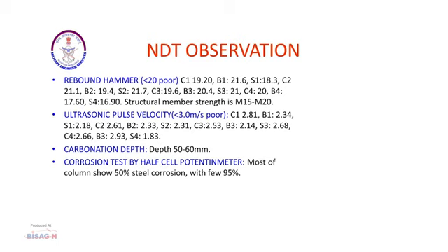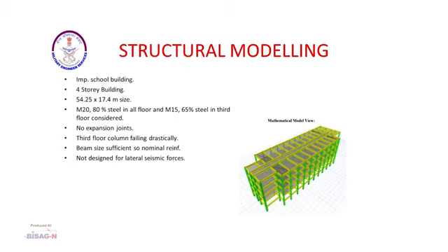That started with NDT testing. We did rebound hammer, ultrasonic pulse velocity, carbonation depth and corrosion test by half cell potential meter. The results of this test have shown that the grade of concrete is near to M20.